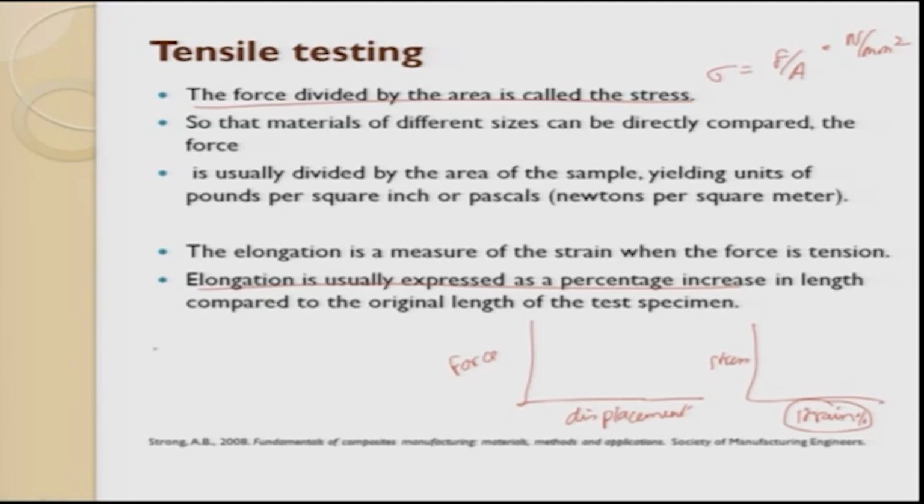Till now we have been happily using only uniaxial tensile testing, that is, a sample tested in one direction. Today there is a concept called biaxial testing, a new phenomenon wherein the loads are applied in one direction as well as at 90 degrees in the other direction.